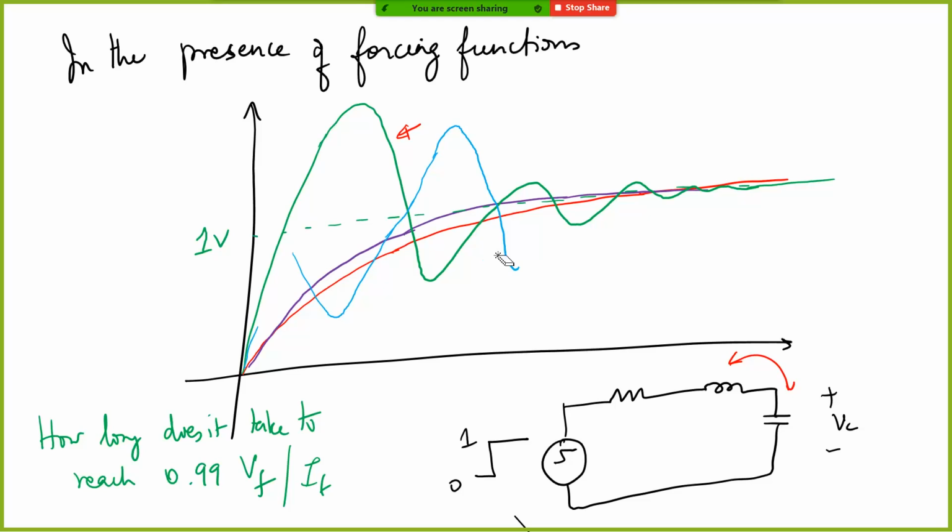So all these things you can basically plot something like this. So this will be your inductor current and this will be your capacitor voltage. You can see these things in LTspice. It's easy to probe those nodes, look at the currents, look at the voltages. So basically the energy transfer keeps happening between the inductor and the capacitor.